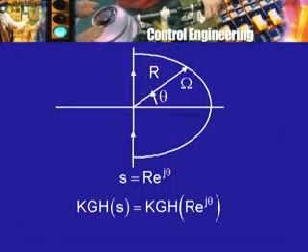So remember, this is why we have to look at encirclements of the point minus 1 plus j0 by the polar plot. Now, going back to the example that I had drawn earlier, we are now to think of the rest of the original contour. Here is this contour once again. What about the image of this part of the contour? This cannot be experimentally determined, because the frequency response method applies only to this part of the contour.